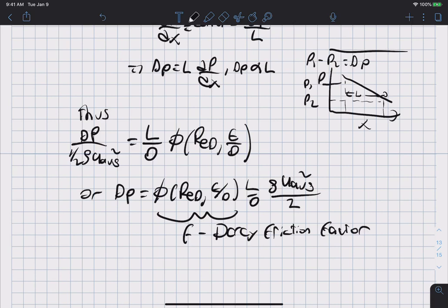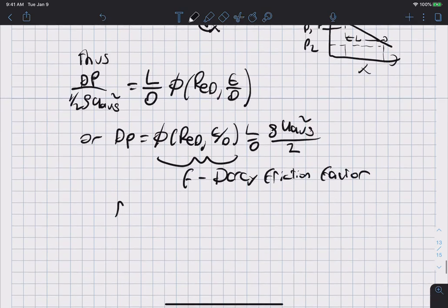Okay, and of course we only know to do this because we carefully analyzed the laminar case, and we're trying to draw analogies to the laminar case wherever possible. So using our results from laminar flow and extending the Buckingham Pi analysis to account for extra features that are important for turbulent flow, we see that delta P is still f L over D times the dynamic pressure.